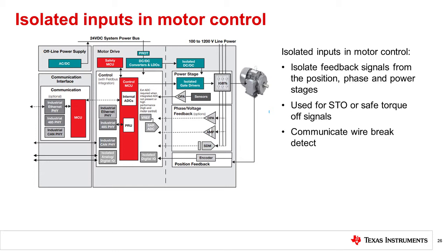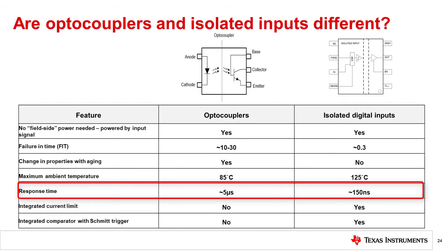In these cases, the speed of an optocoupler can often present a challenge due to limiting data rate. Propagation delay for an opto ranges in the microseconds, and a delay in response time can be critical in the use case of monitoring position feedback, which could risk instability and control of the feedback loop.